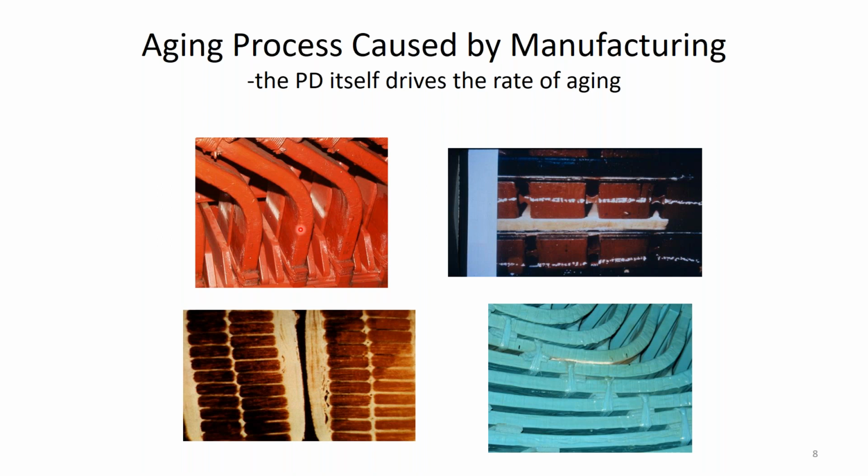The PD itself hardly ever caused failure. Here's a case where the manufacturer kind of forgot to put the epoxy in. So this is the copper conductors, the insulation here, and you see voids that are in there. Still took many years for this to cause failure.